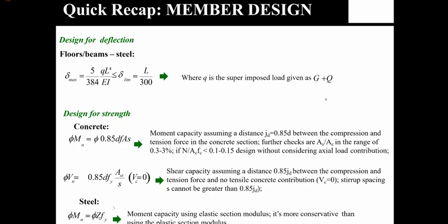Similarly, if I ask, how do you compute steel member capacity? It's nothing but yield capacity times section modulus. It could be plastic section modulus. You can conservatively take elastic section modulus, right?